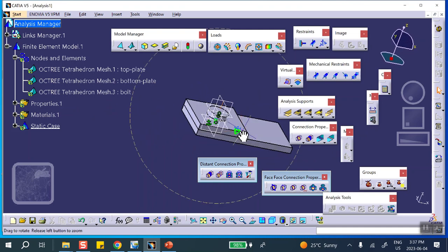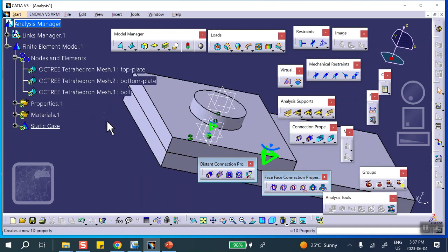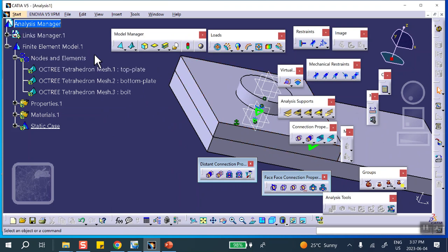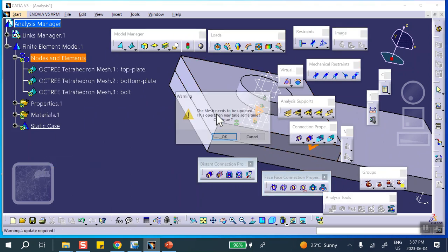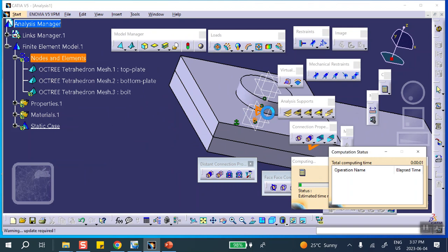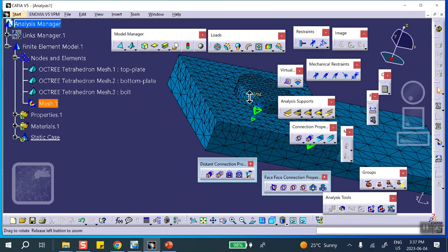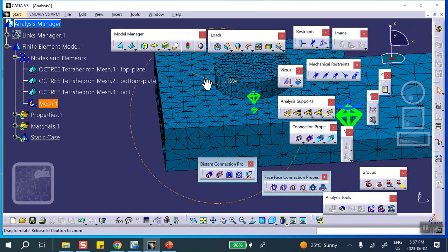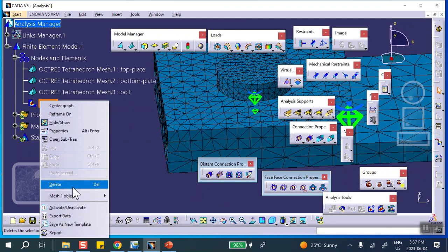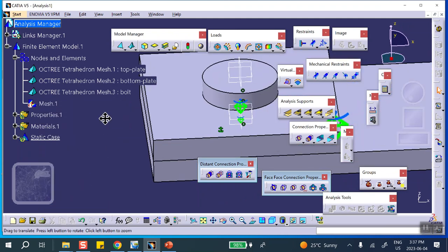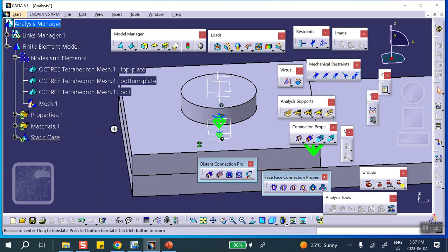Now, first thing first, if you want to see the mesh, you can generate it. I mean, basically look at the mesh if you want. Remember, we're not using symmetry because that requires passing through the bolt. So deactivate that horrible mesh. So we're going to clamp these ends.